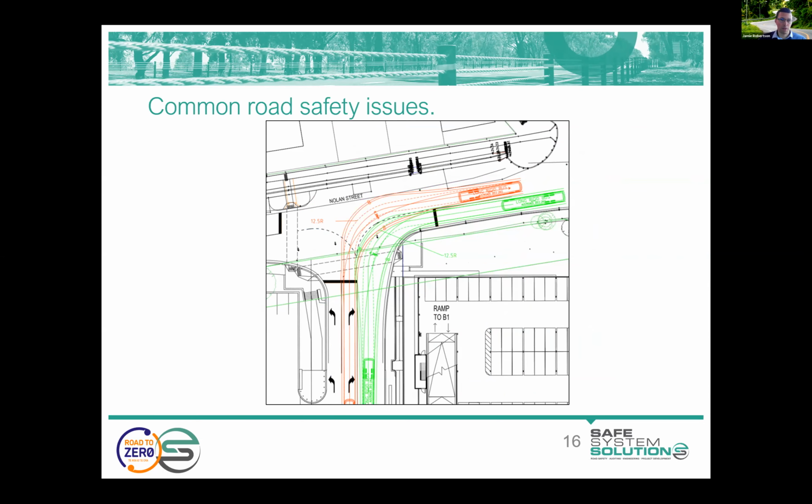So that's between vehicles. You also need to provide a buffer between those turning vehicles and curb lines, any roadside furniture and so on. So plotting that offset line can help you determine if you do have that required buffer.